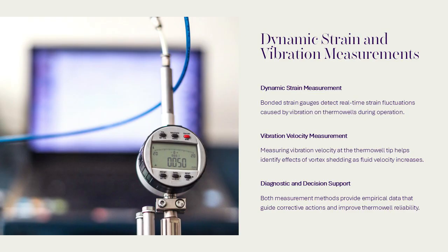Dynamic strain measurements using bonded strain gauges provide real-time insights into thermowell performance under operational conditions. These gauges detect strain fluctuations caused by vibration, helping engineers assess the severity of dynamic loading. However, installation during operation is challenging and typically requires specialized skills and equipment.